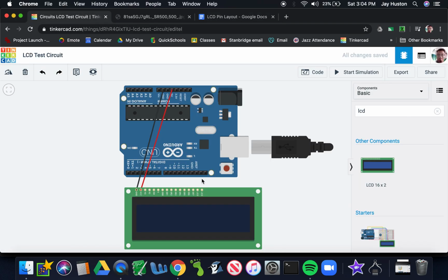So I'm going to come back here. I'm going to go out to 15, which, hey, it says anode. Hey, I remember that from LEDs. That's where power goes in. So not the last one. That's the cathode. One in from the last one, the anode. I'm going to click on that. I'm going to take that right up to 5 volts also.